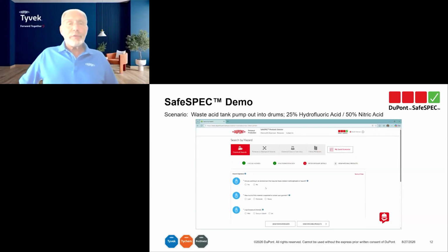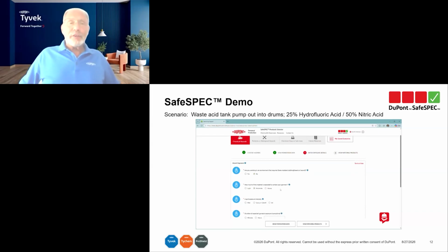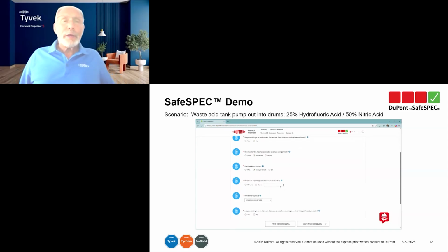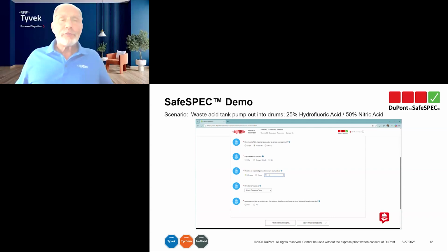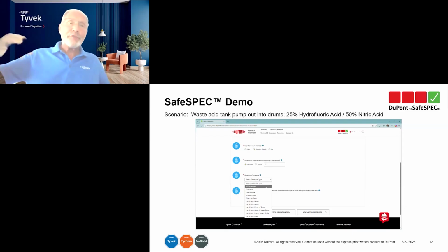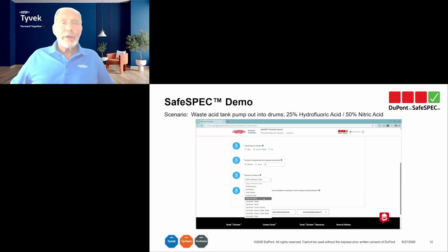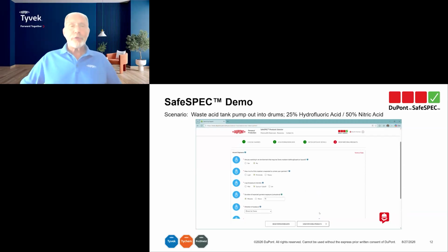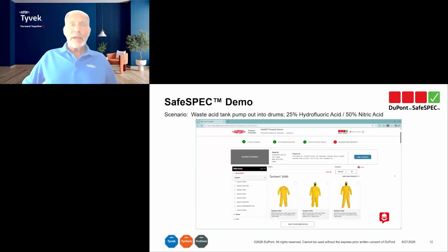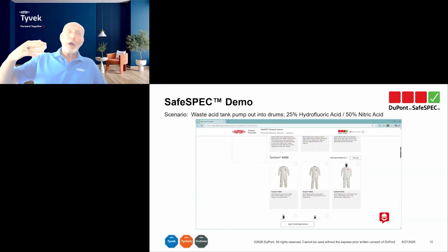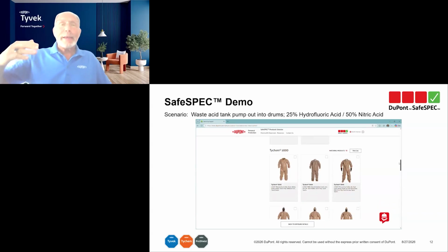A series of questions defines our exposure scenario. First, asking, is there a fire risk? The answer is no in this case. We're going to pick moderate spray splash as the hazard risk. 15 minutes, understanding that if anybody gets exposed, they stop, they go to a safety shower, and they rinse off. And as far as the direction of exposure, direct to the torso. And do we need biological protection? The answer is no. We click the next step, and then we get results of DuPont products that meet the scenario,